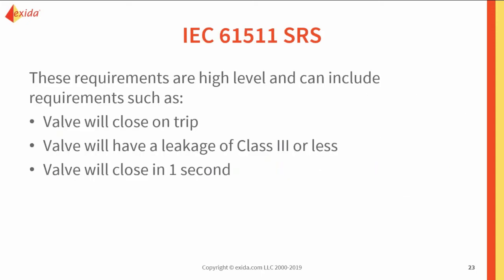As I said, when you think on the end user's level of IEC 61511, we're thinking of what that device can do. So when we're talking about an SRS and what's important pieces of information for that document, the end user wants to know if the valve needs to close, it can do so. If it doesn't need to leak, it will make sure to not. If it is a tight shutoff application, it can achieve that low level of leakage. If the valve needs to close within 1 second, it can do that job when required.